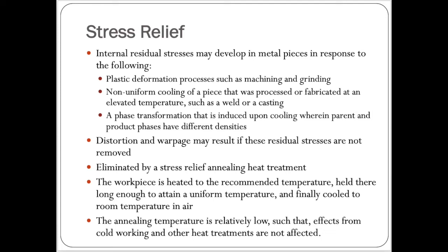Distortion and warpage may result if these residual stresses are not removed. They may be eliminated by a stress relief annealing heat treatment, in which the piece is heated to a recommended temperature, held there long enough to attain a uniform temperature, and finally cooled to room temperature in air. The annealing temperature is ordinarily a relatively low one, such that the effects resulting from cold working or any other heat treatment process are not affected.